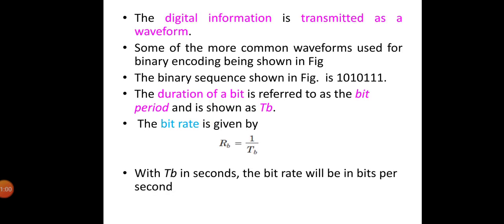And now in this video, let us discuss the characteristics of some more common types of digital baseband signals, along with the representative methods of digital modulation. Keyboard characters, for example, are usually encoded in binary digital code. A binary code has two symbols, usually denoted as 0 or 1. For example, teleprinter code may use the combination 110000 to represent the letter A.